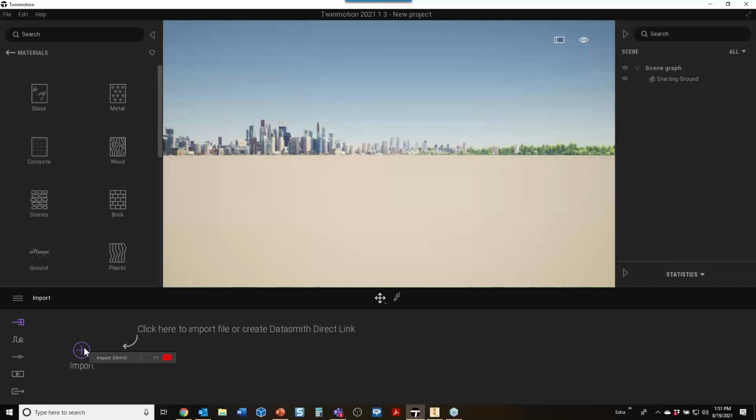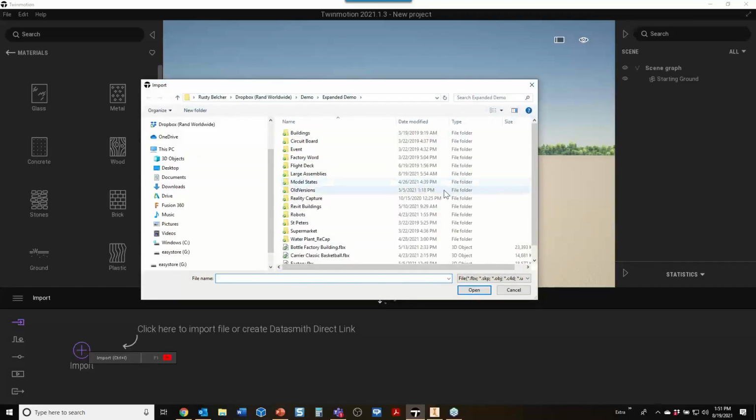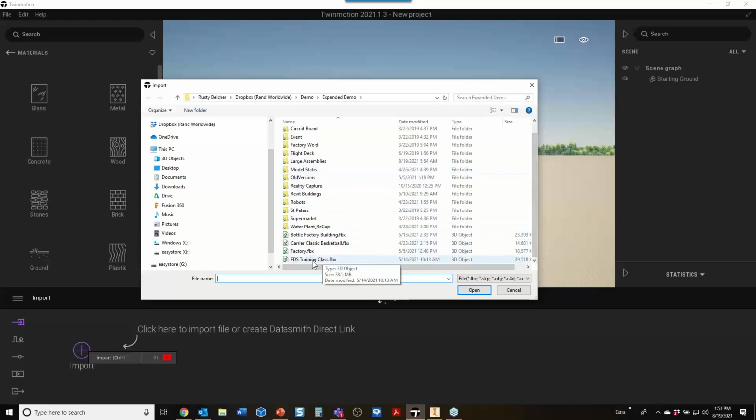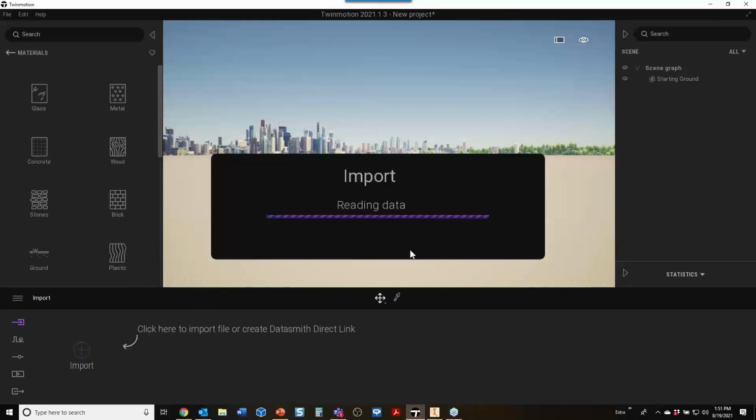Now this import, I want you to understand, when I put my stuff into Navisworks, to get the stuff into Twinmotion, I simply need to export from Navisworks as an FBX file. So Navisworks will produce that FBX file, and then I can bring that right into Twinmotion. And this is that. So it is a big model. This is real data, fairly big model. A couple of buildings worth of factory floor that I'm bringing in here, and it comes in, I think, very quickly.